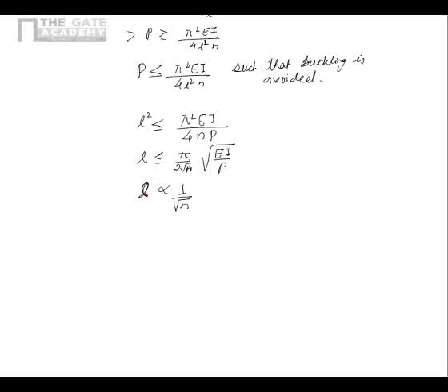So this is a very important problem in the design of many mechanical structures, for example the connecting rod of an engine, which is half of the time under compressive stress. It has to be designed with such a consideration, because the loading is very dynamic, and the length has to be such that the dynamic load is borne properly, because dynamic load is much higher than the same static force. With this we end the chapter on buckling, and later on we will see a lot of problems which have come in GATE.